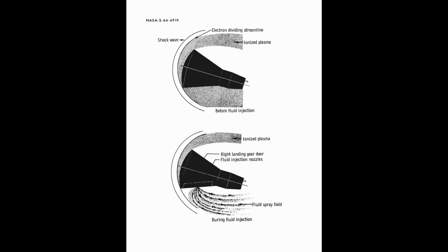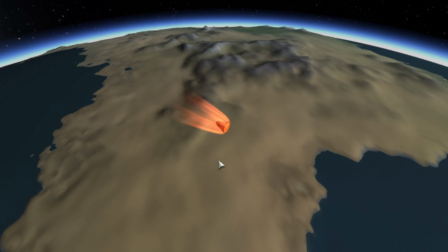Capsules are also symmetrical airfoils. While capsules are descending through the atmosphere, they are producing lift that is going upwards. This makes it so that the capsule will spend more time in the upper atmosphere, where they can bleed off speed while experiencing less atmospheric heating.